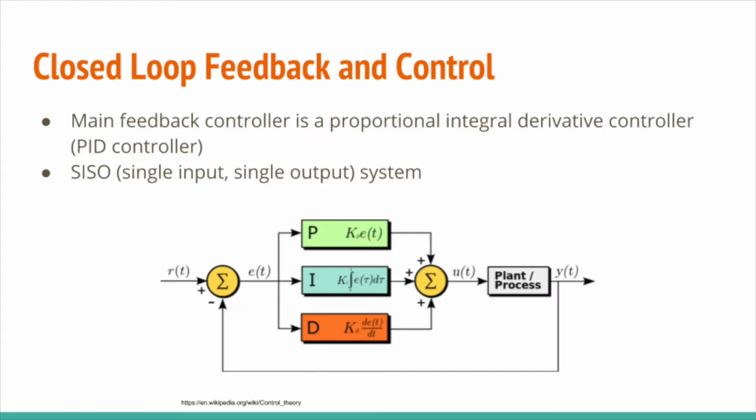The system uses a proportional integral derivative controller, also known as a PID, as the control loop feedback mechanism. The PID continuously calculates an error as the difference between a desired set point and a measured process variable and applies a correction. The PID algorithm calculates the error between the angle theta and the equilibrium position and outputs the torque required to maintain balance and not tip over.